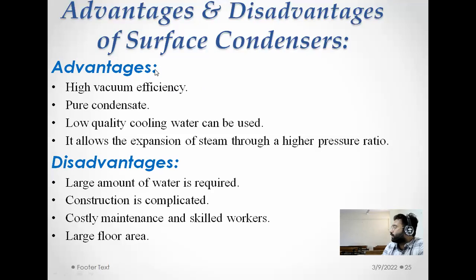So I will write. In the case of a condenser, it is assumed that steam is flowing inside the condenser and the steam is condensed to water. So the pressure of the condenser is assumed to be equal to the steam pressure, or pressure of steam. Now in this case, what happens? Sometimes there is air leakage. Air gets in along with the steam, inside the condenser.